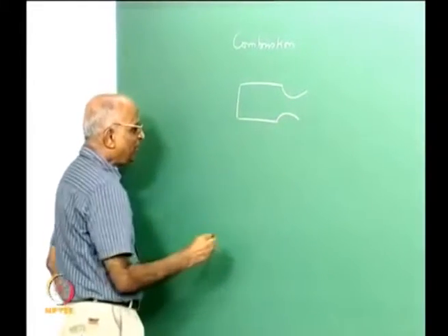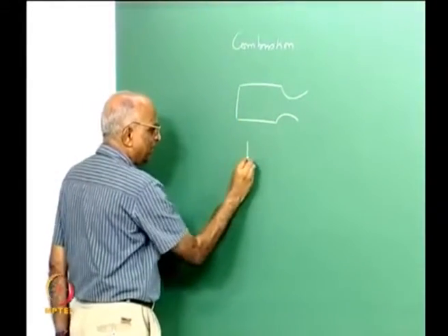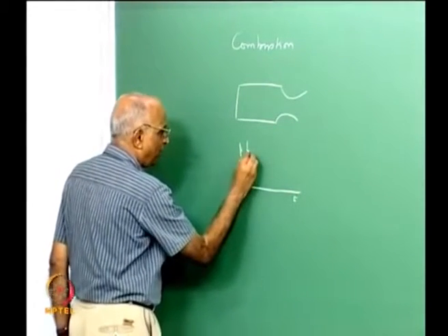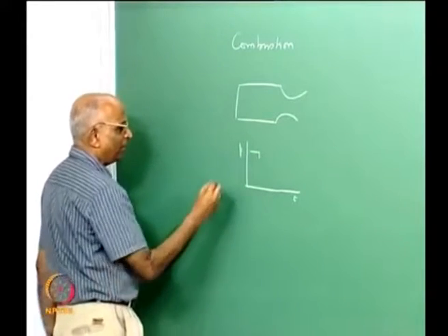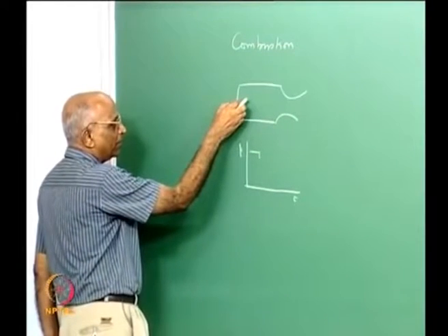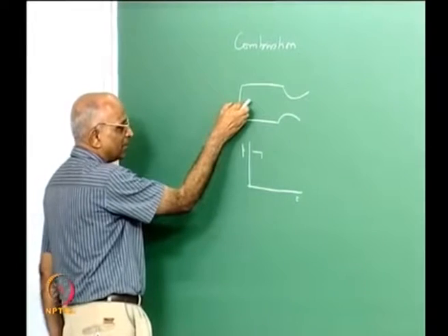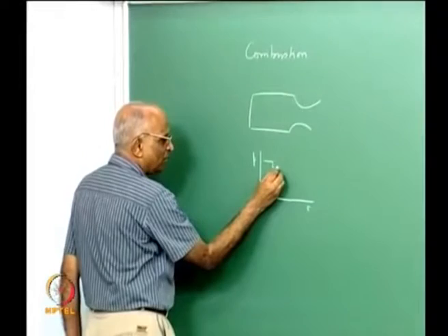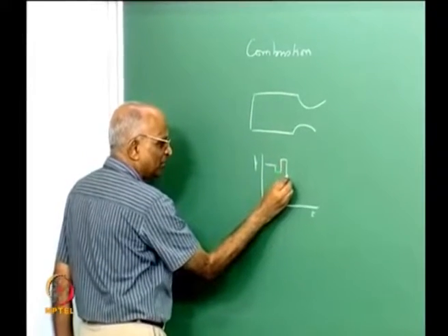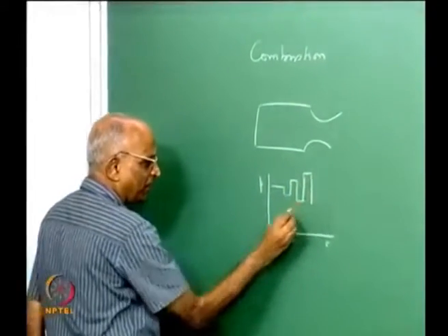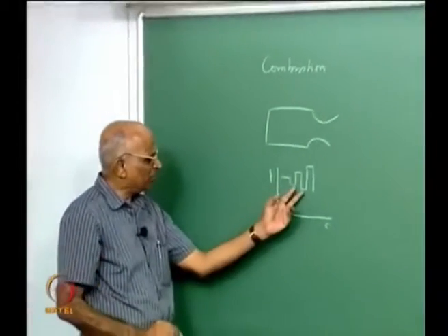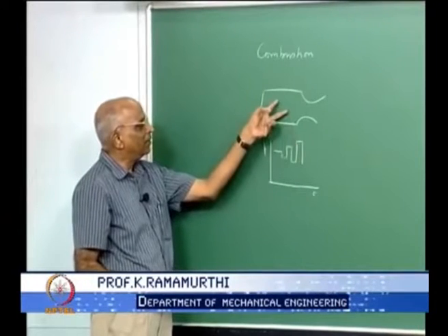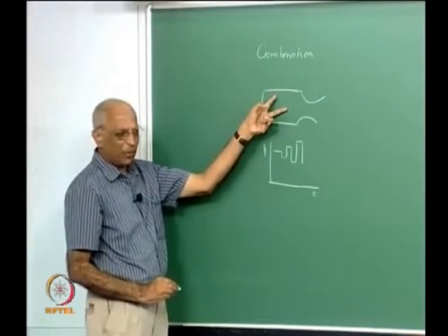We told ourselves that if, by chance, the steady pressure in the rocket, pressure versus time, falls in some way, and if the pressure drop across the injector is less than some value relating to the chamber pressure, it is always possible for the oscillations to grow with respect to time. We also told ourselves that this is something like a diverging oscillation, and the pressure could reach a level wherein the case may not withstand it, and it is a problem.